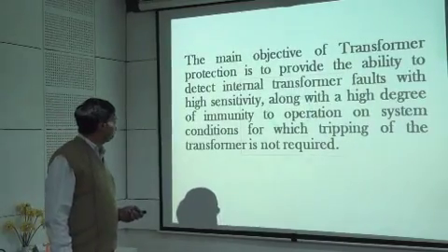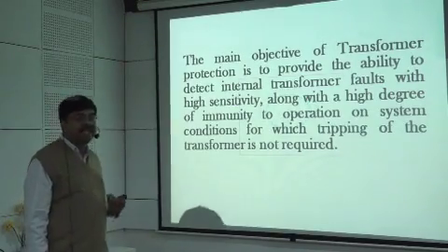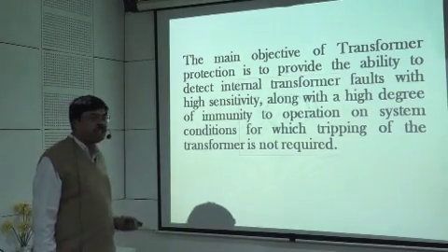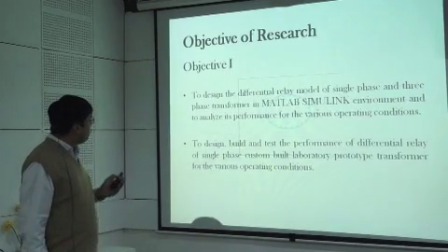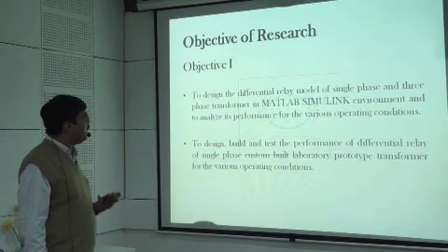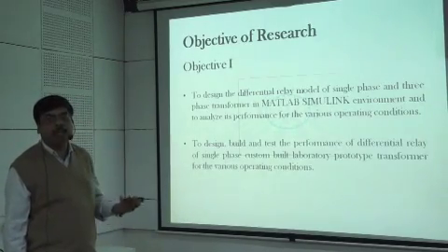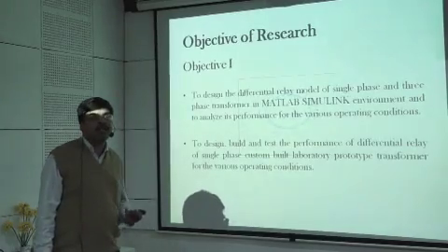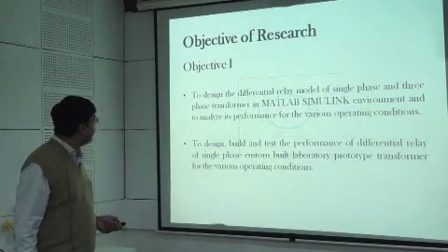The main objective of transformer protection is to provide the ability to detect internal transformer faults with high sensitivity along with a high degree of immunity to operation on system conditions for which tripping of the transformer is not required. The objectives of my research: first objective is to design the differential relay model of a single phase and 3-phase transformer in MATLAB Simulink environment and to analyze its various operating conditions. To design, build and test the performance of differential relay of a single phase laboratory custom built transformer and to analyze its various operating conditions.